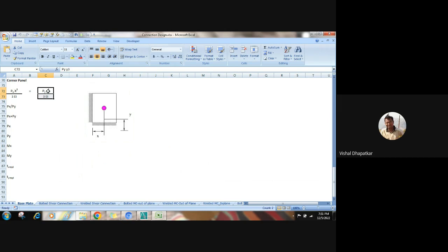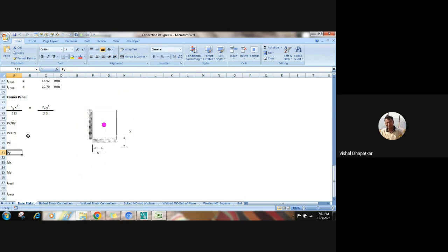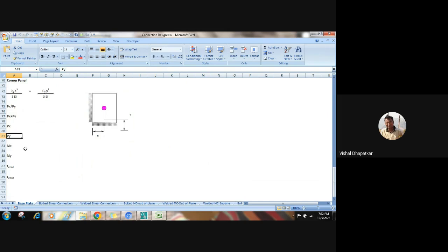After comparing these two, again we will get the px and py ratio, and we know px plus py are the total tension in the bolt. So again, solving these two equations, we'll get the contribution of force by that edge, and again getting the moment from these two forces, cantilever moment we will get for px and py, and we'll get the thickness.